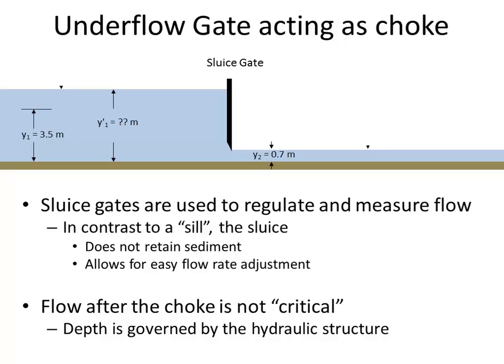Comparing energy. So what we'll say is, when do you think the water level will stop rising? When the energy is basically equal. That's right. So E1 prime will equal E2. It's going to keep choking until there's enough energy that it can get under that gate. As soon as it can achieve that, then it'll stop getting deeper. So what we need to do is we need to say